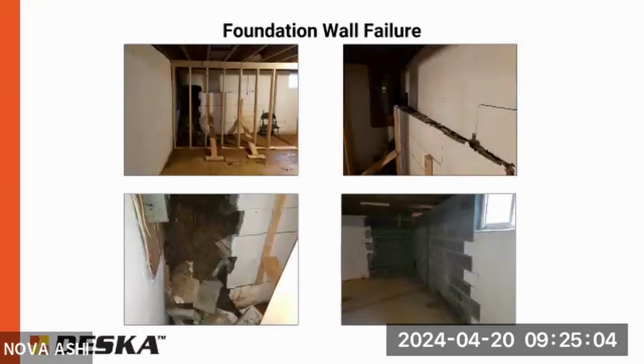Here's another example of a wall failure. As opposed to the last slide, usually when foundation walls fail from lateral inward deflection, it's not the entire wall at once. Usually it's in isolated areas like this, in terms of how it actually collapses. But this particular wall had to be replaced. I think it was about 25 feet or so when you include the two faces.